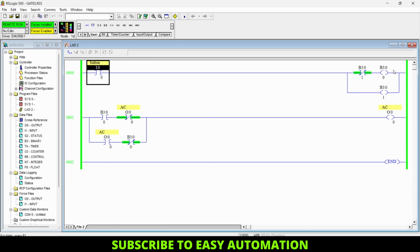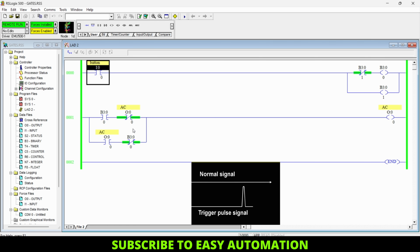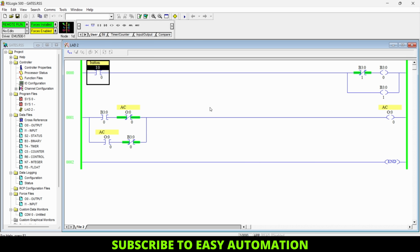So that's why this bit will go high before this one, and whenever this bit goes high, this bit is low. But when this bit goes high, it will immediately cut off the supply for this bit. So that's why this bit has only a few milliseconds to blink. That's why this bit gives us the triggering pulse, and that will be used for this NO contact and this NC contact as well. So now you know how this trigger pulse is generated.